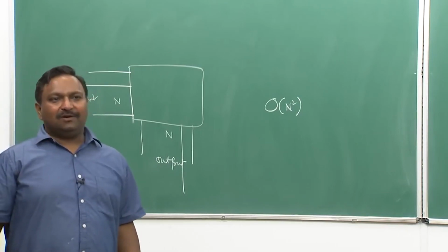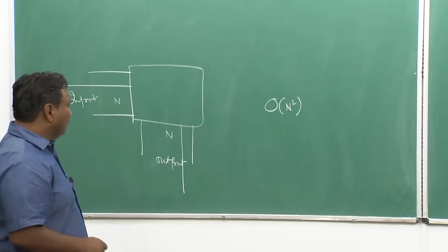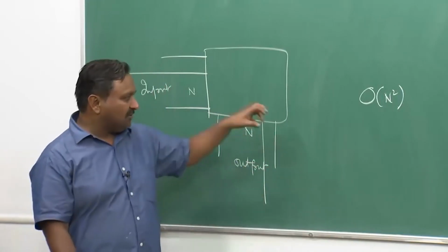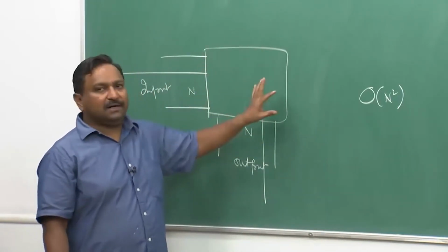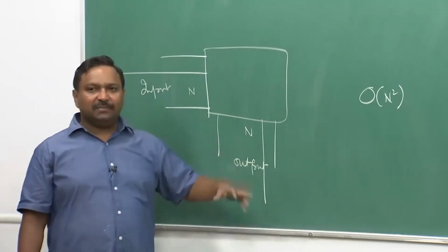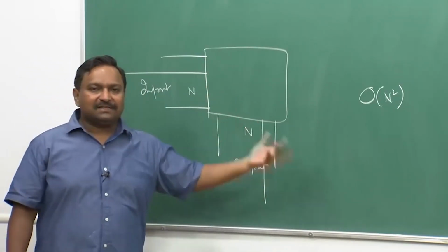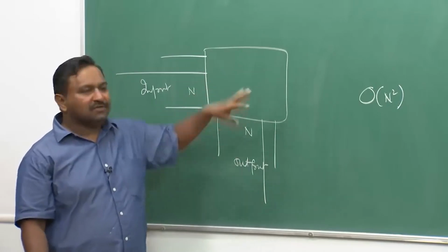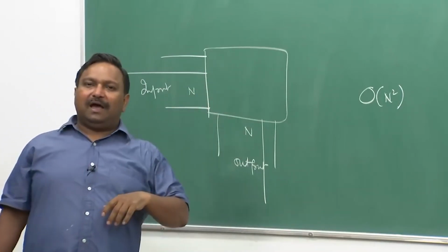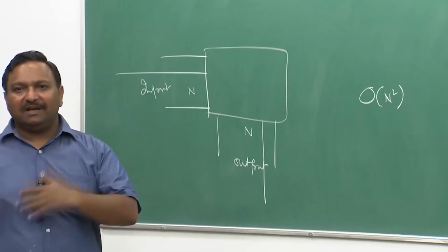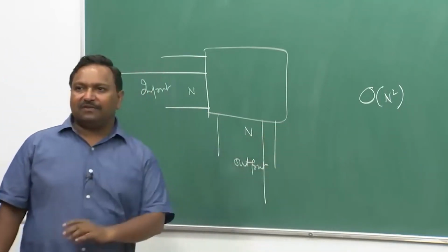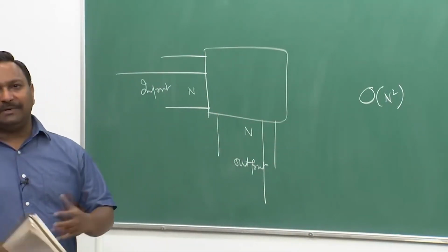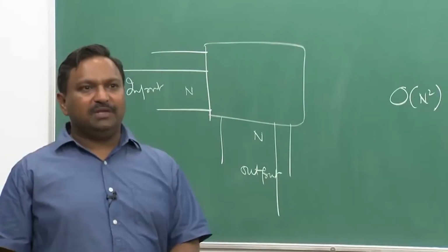Okay, people should ask why not, probably we can do that, but you have to understand that all these cross points have to be controlled by a controller, and mostly there will be one controller per crossbar. So whenever a connection request comes, it will process it and set up a connection. It does take some computing load. So as my size grows, my computing load also grows, for managing the cross points. So after a certain size, if you keep increasing the size to a very large value, the controller which is going to control the cross points will not be able to take up the load. So you cannot arbitrarily increase your size; it has to be limited.